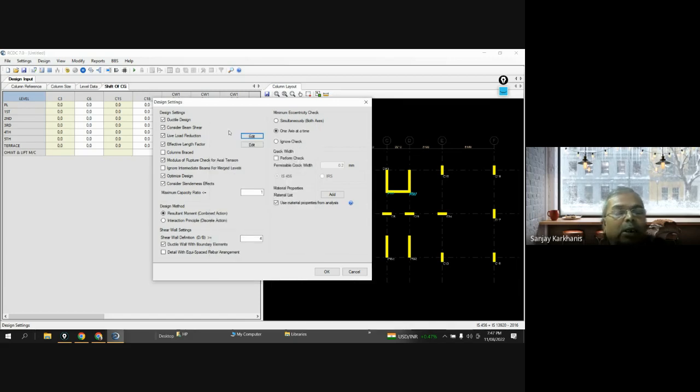So that reduction for live load in analysis, that too for earthquake analysis, is for calculation of seismic weight, and based on that we are finally calculating base shear. So that is the analysis part. And here in design part, whatever loads are there up to that level, they are automatically reduced if you apply this. So if you do not apply, then it will not consider a reduction.